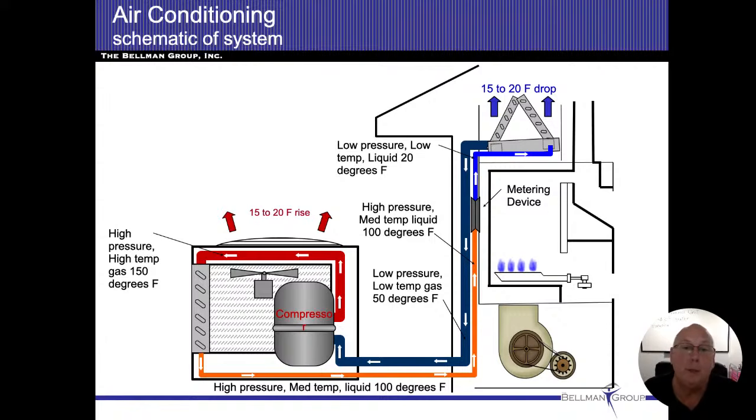If you look at this carefully, you'll see that the compressor, and I'm not talking about the fans that blow the air over the coils, is really the only moving part of the air conditioner. So as I'm adding pressure into the system, I'm also releasing pressure at the metering device. And those things are supposed to be in tune perfectly.